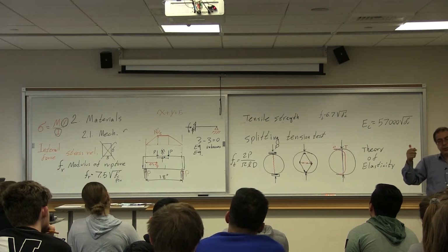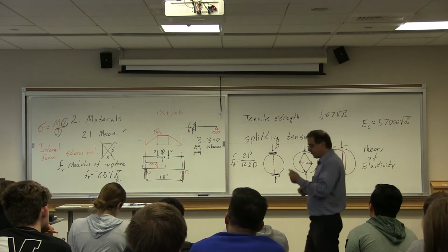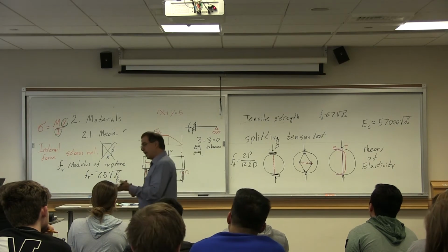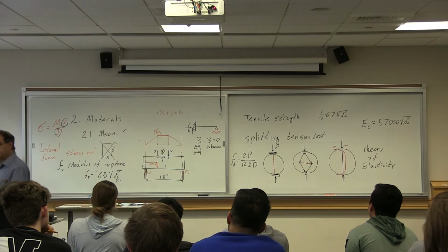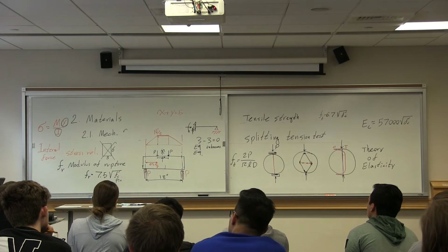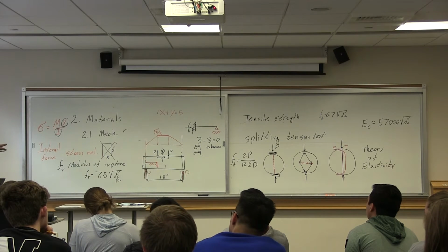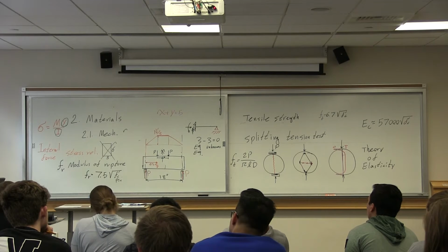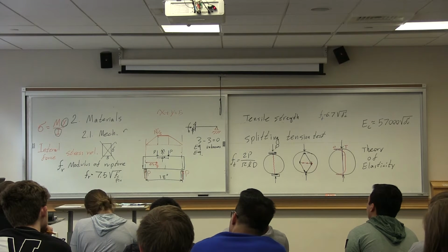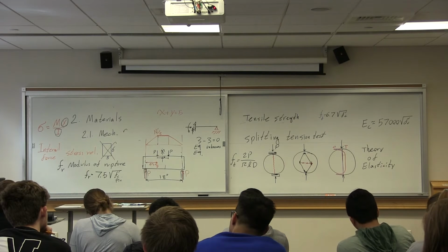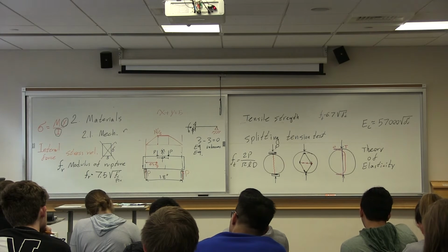So if the number of equations is less than the number of unknowns, then you have infinite solutions. Correct? Everybody agrees? Now in this case, after adding that support, the number of equations is 3, the number of unknowns is 4. Conclusion? From a mathematical point of view, if that is the statement of the problem, we have infinite solutions. Everybody's on board so far?